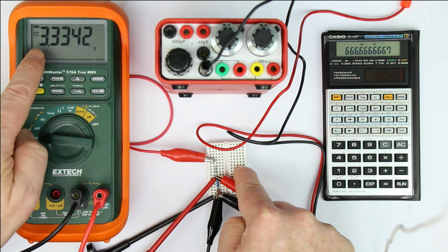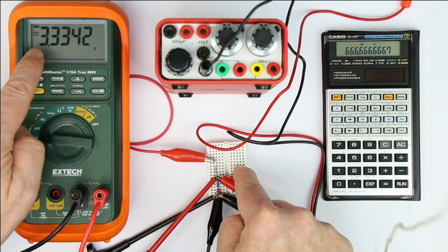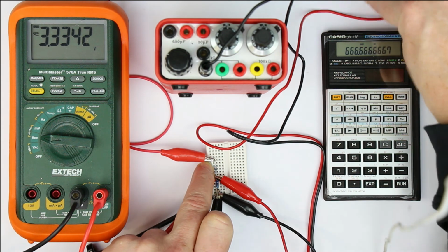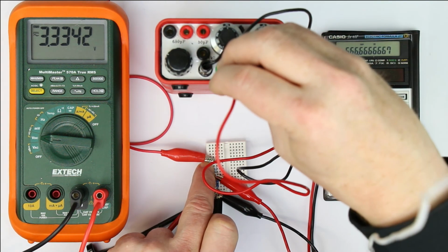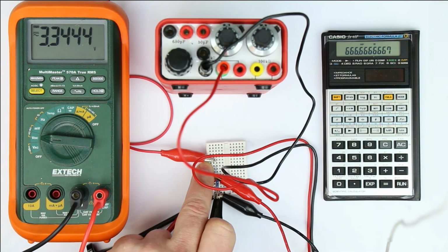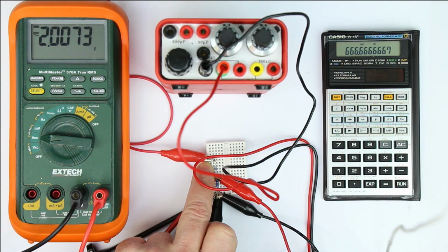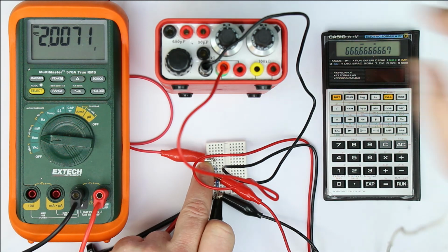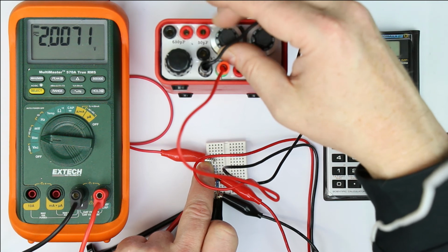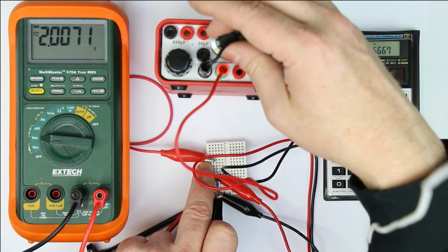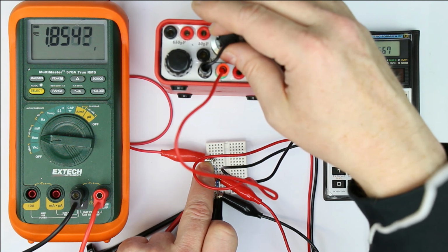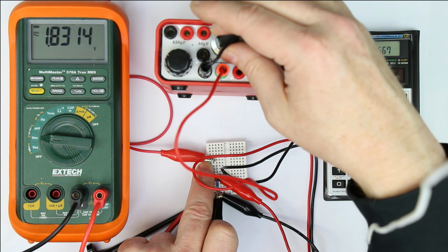And now let's see what happens when we connect our variable resistor box. We have to find the point where the voltage again drops to 1/2, which would be 1.666 volts. And I've set it as a starting point to its maximum value of 1K. We see, after waiting a little bit for acquiring the measurement value, it already drops to 2 volts, and now we turn back the resistance until we get 1.666 volts.